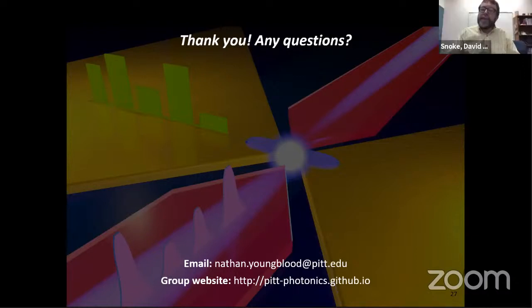What's the time scale for that transition? What really limits the speed at which you can read and write? Really the cool down time. So it really depends on what you're using to switch the material. You can use picosecond pulses or less in the optical domain, because you can heat up really efficiently with optical absorption. Electrical domain, it's more on the order of tens to hundreds of nanoseconds. So there have been demonstrations with less than a nanosecond pulse width for crystallization and amorphization.